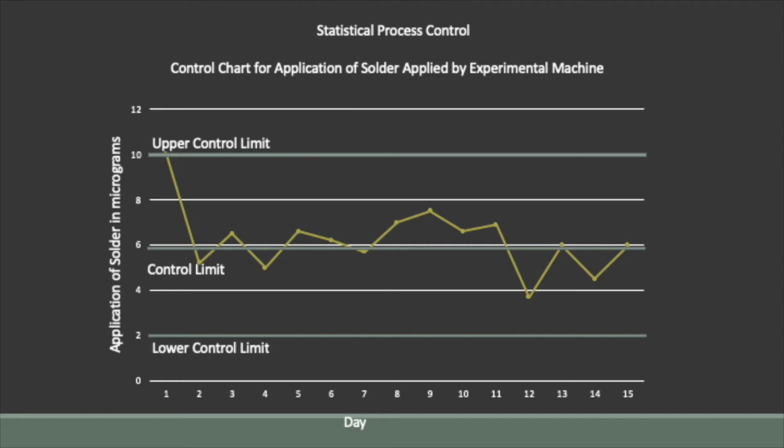Control charts tell us whether or not a system is in a state of control or stability. These charts portray this information by plotting some statistics such as mean solder application over some time period. A central line that represents the mean of the statistic is drawn to show how an instance of the process compares to the average. Upper and lower boundaries are shown on a control chart to show the extremities, usually in terms of 3 standard deviations.